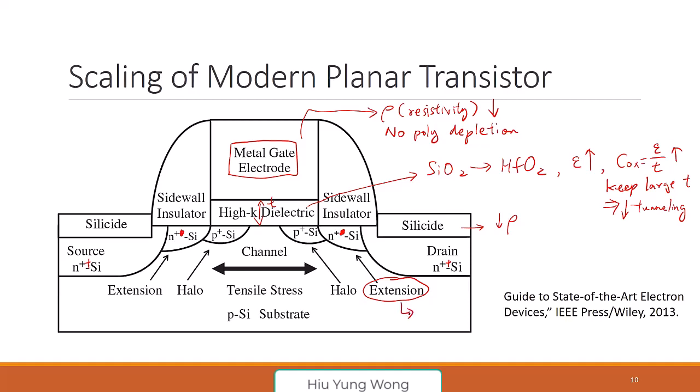Why do we need that? It is just to reduce hot carrier injection, right? We will study it a little bit in memory because we use hot carrier injection to do programming. But basically, this is to increase the reliability, which is called HCI. If you love device physics, just try to understand, okay?